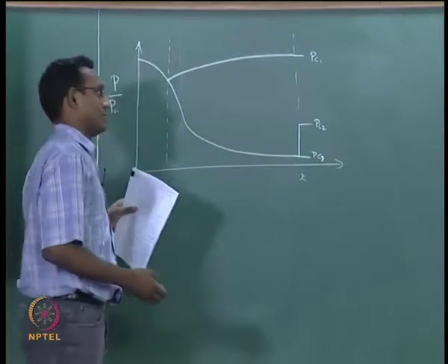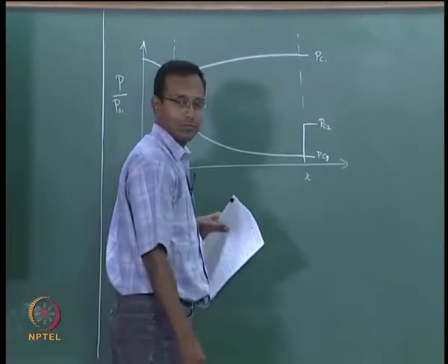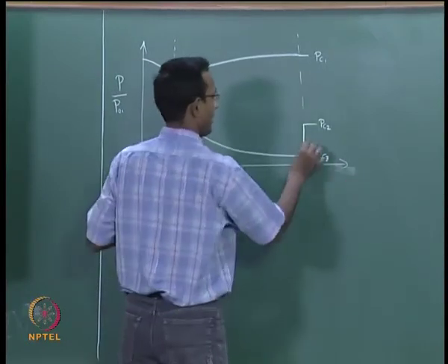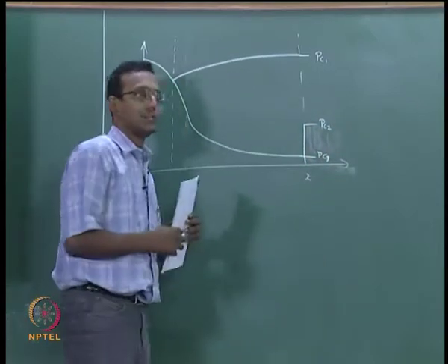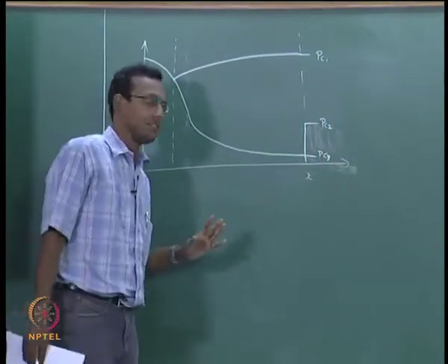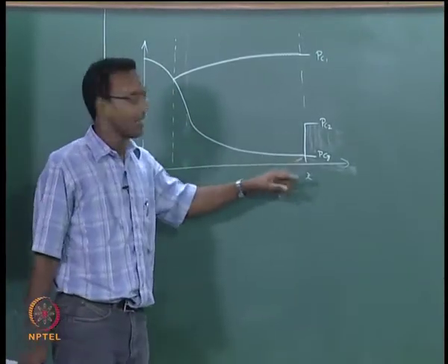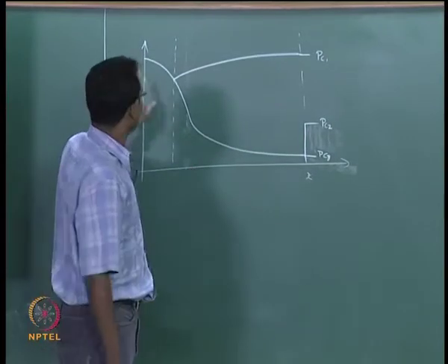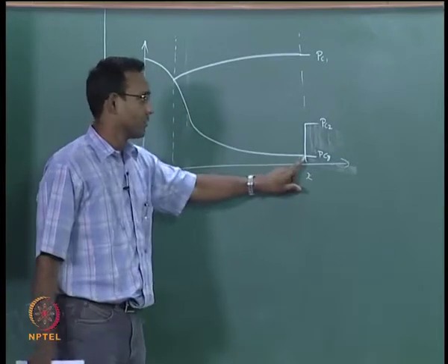We did all this, and then we said that if I decrease my pressure below this value, this particular region is called under expanded region. If it is in this region, it is over expanded region, and since previously we were interested only in pressure profile inside the nozzle, we said that anything below P critical 2, my pressure distribution inside the nozzle will never change, it will always be this particular curve.